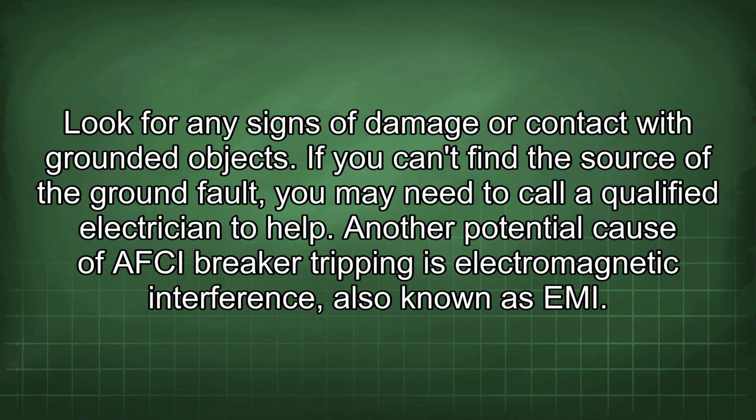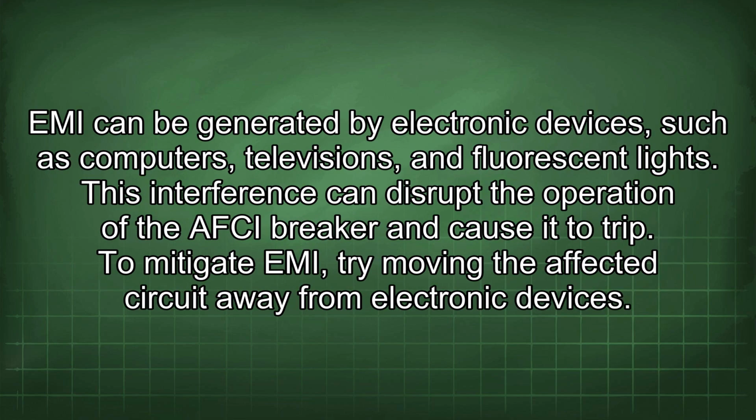Another potential cause of AFCI breaker tripping is electromagnetic interference, also known as EMI. EMI can be generated by electronic devices such as computers, televisions, and fluorescent lights. This interference can disrupt the operation of the AFCI breaker and cause it to trip.